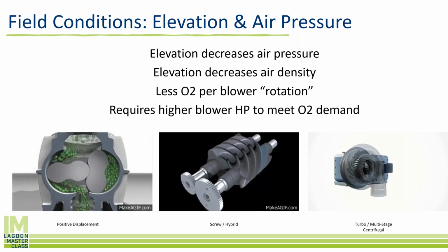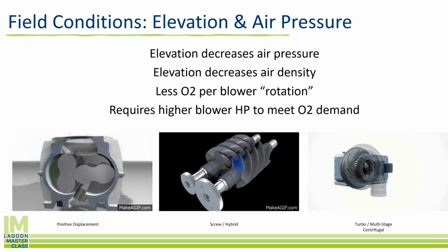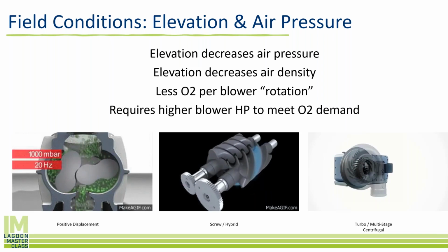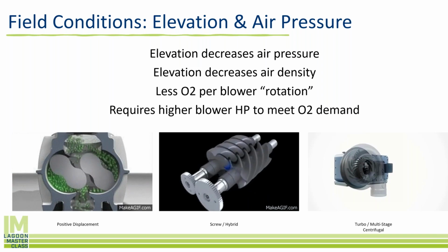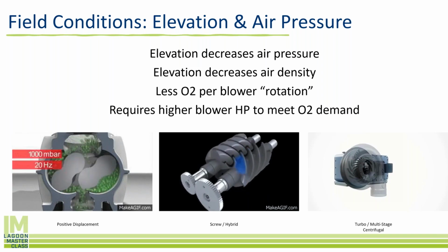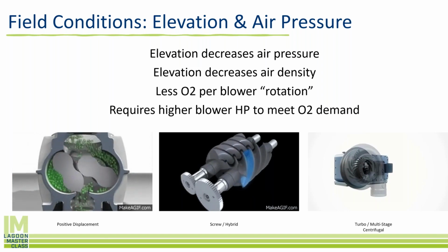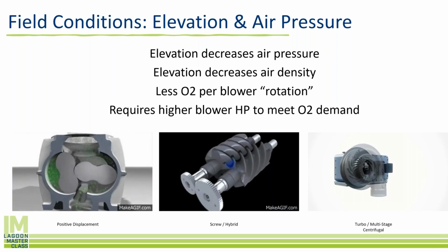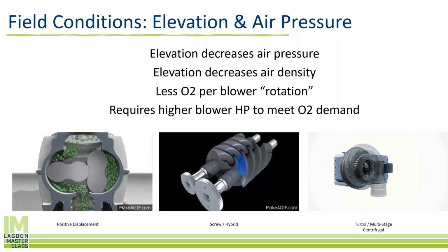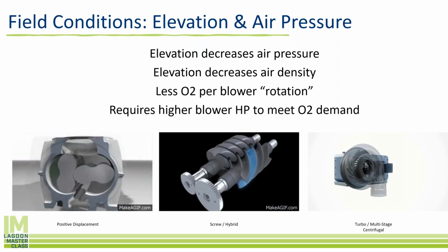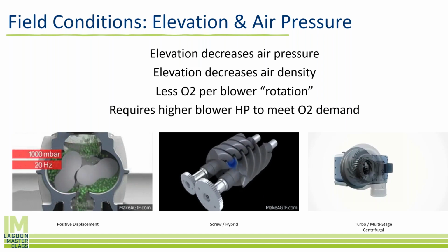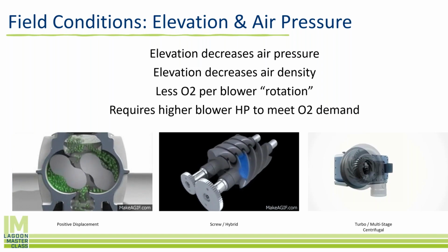The oxygen up in Denver might be 19% or 20%, where the oxygen down at sea level is 21 or 22%, simply because the air is less dense in Denver. So if you have a blower at a lagoon system, it takes more blower rotations to move more of the less dense air to get the same O2 demand met. So just note that with elevation and air pressure changes, you will get a difference in airflow. This is a conversation for a different webinar, but something worth keeping in mind while we're talking about hydraulics.